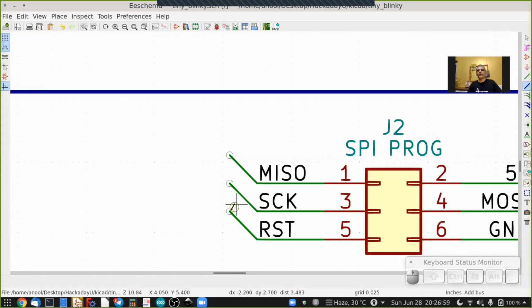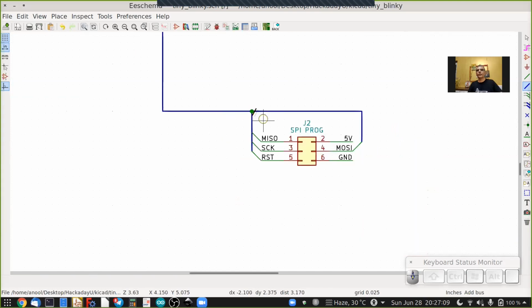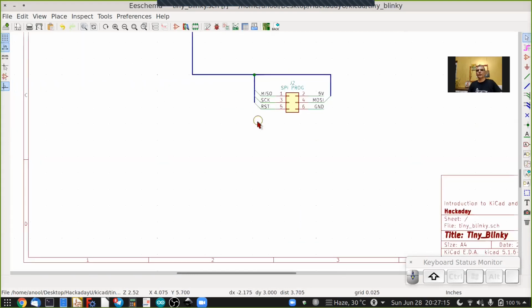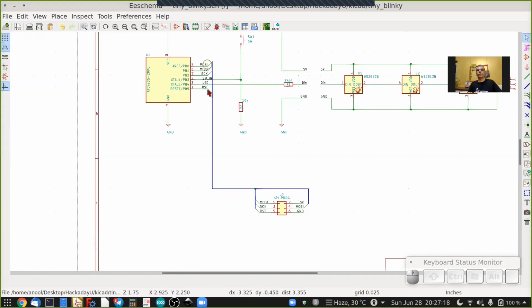So we'll have to add a bus connection from here to this bus using the same tool. Start from here and I end it over here. And it added a bus to bus junction over here. So now what KiCad has done is take these 4 wires from here and pipe it through a single common bus and then spread it out over this program connector.